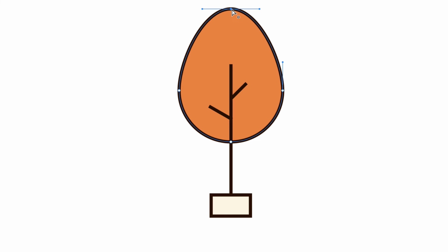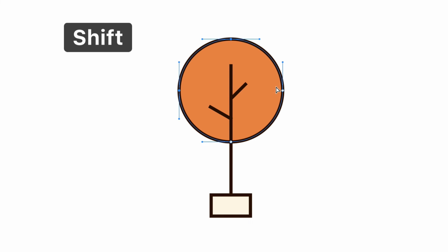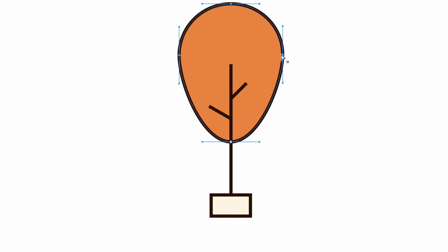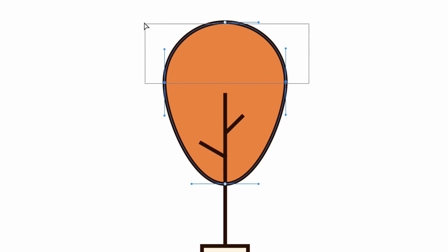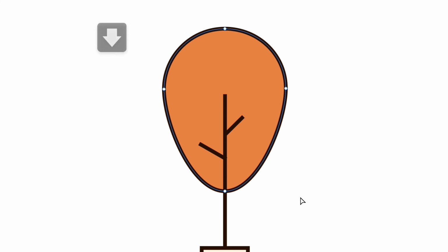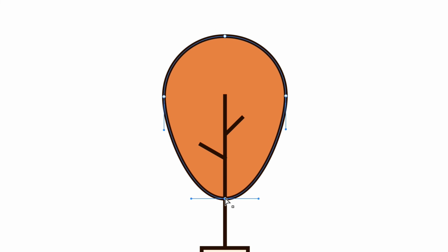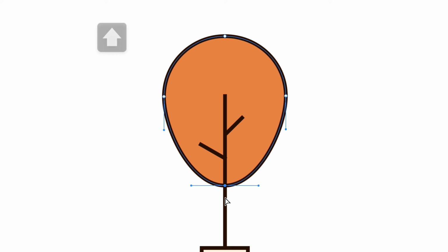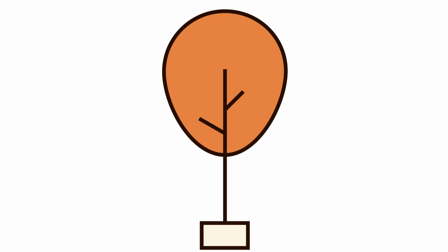You can also move multiple points at the same time. You can select several points in the same way as we used earlier with objects. Click on one point after another, holding the Shift key. Another way is to select points with the selection frame. Note that once you selected any shape or points, you may always move them using the arrow keys on the keyboard.